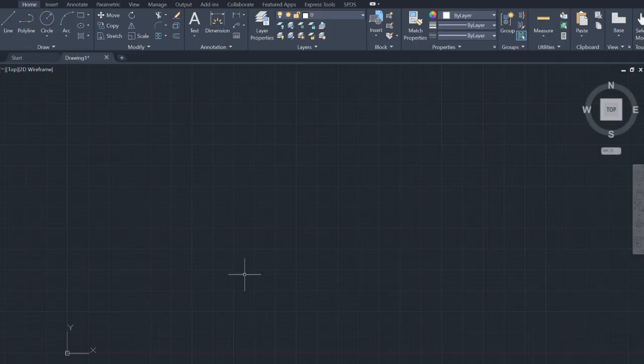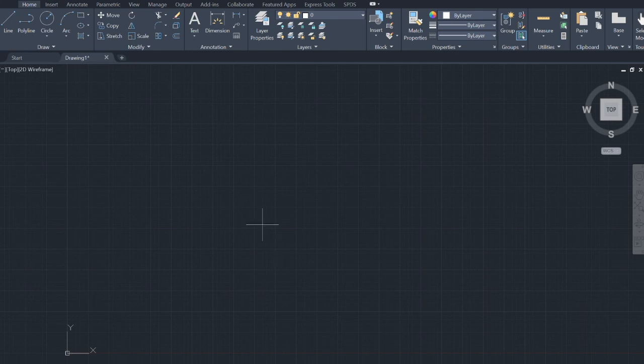First, probably the most used by beginners, you will see it in the ribbon, in the Draw panel, where you will see Line. You can use that. So, when you click that line there, your command bar will automatically ask you to specify your first point. But let's not stop there, because there are other ways to make a line.